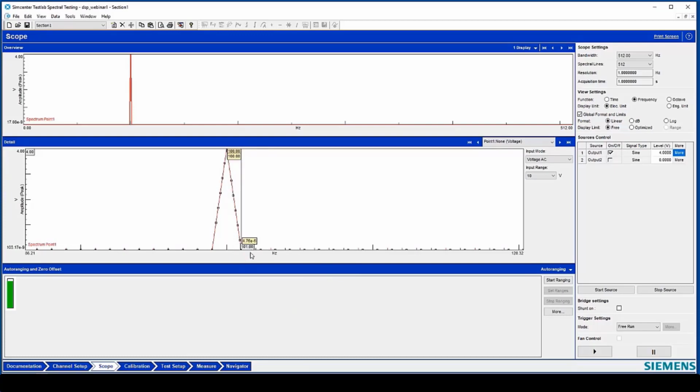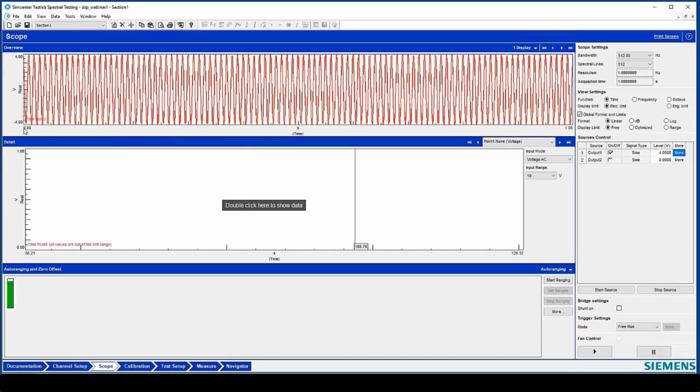Over here at 101, I am at 0 or something very close to 0. And then it's 0 from there out. There's really no data in between. It's just connecting the line. So what I have is a 1 hertz resolution, Charles. Does that make sense? Yeah. And if I look in the time domain, that 1 hertz resolution is 1 second long. So you can see here it goes up to 1 second.